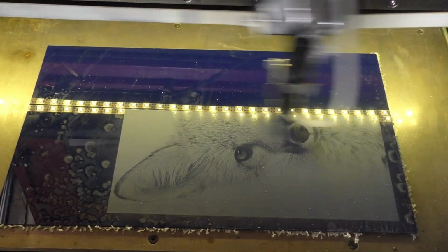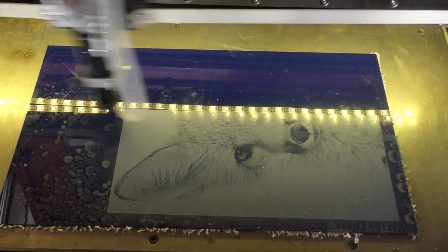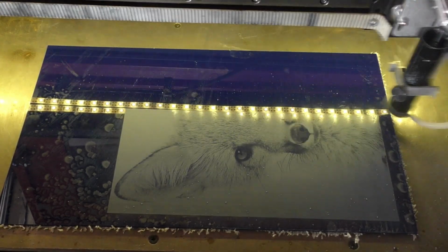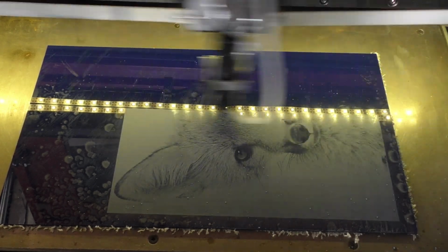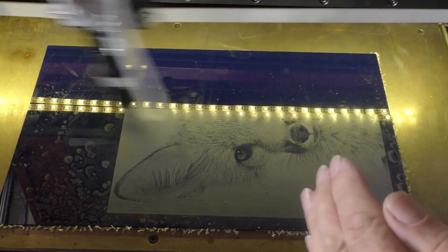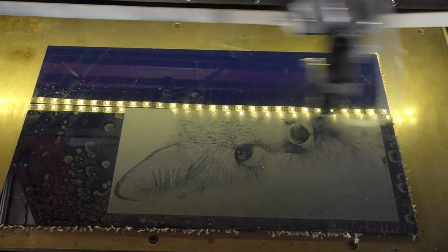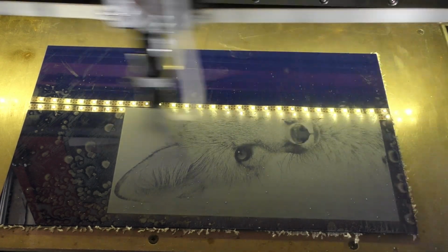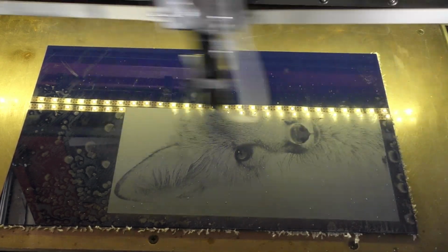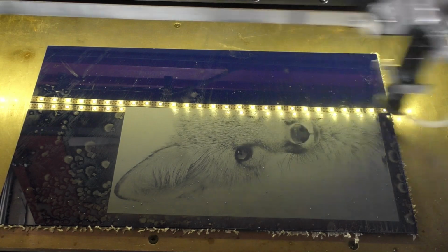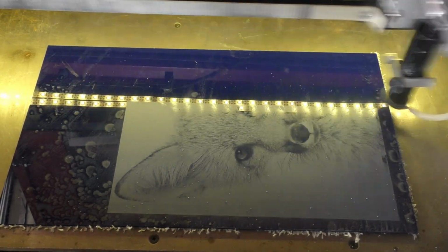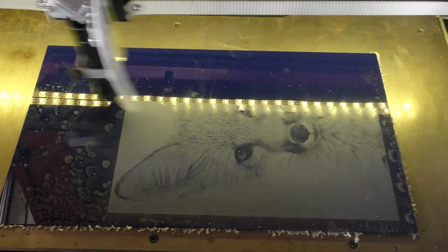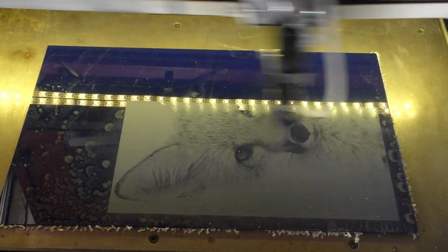So basically I've used my checker pattern to do 2 things. First of all, to try and get rid of the aliasing, and secondly, I've been very accurate in the way in which I've set my scanning offset up. Because my scanning offset is now set to better than 0.1 of a millimetre. In fact, it's set to 0.05 of a millimetre. I'm running this at the settings I use for my checker pattern, which is 1000 millimetres a second as opposed to 1200 millimetres a second, which I did for the first one.